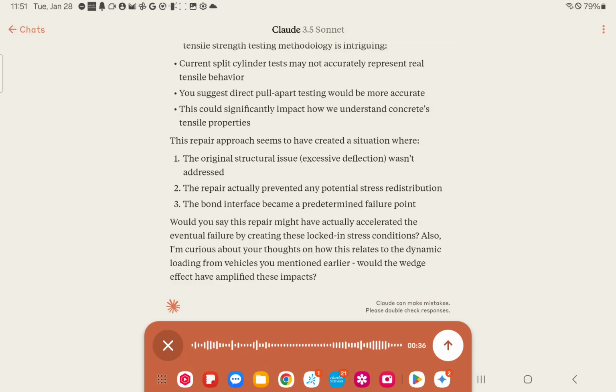I only need to move a few millimeters of deflection down to open up the underside a few millimeters. But to do that, I'm going to need to either elongate the reinforcement down below to have it open up, or I'm going to have slippage. I don't think there was slippage.